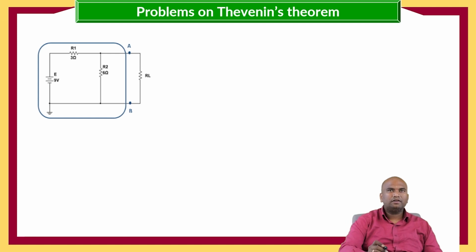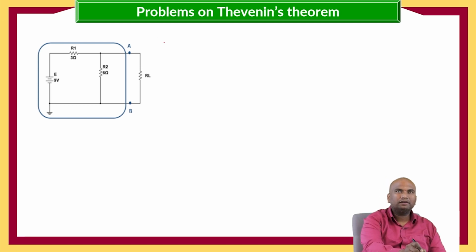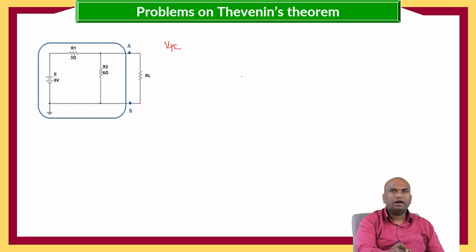So here, first let us calculate the VTH. For VTH calculation, I am making the RL open circuit. I am making the load resistance open circuit.